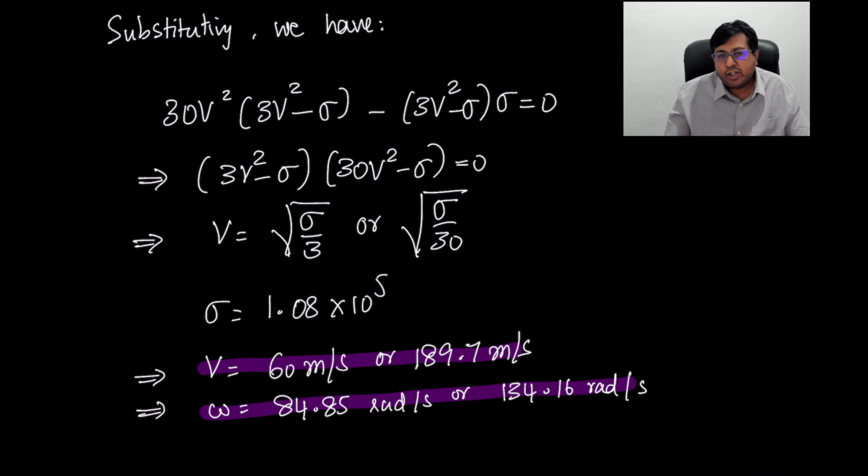Overall, to summarize everything that we have done so far, we started out assuming that we have an airfoil undergoing a heaving and a pitching motion. Heaving motion is up and down, pitching motion is a rotating, twisting motion. We thought of this as a 2 degree of freedom system in order to derive our equation of motion. And then we asked, what if we have a general equation of motion? Using the simple airfoil, we tried to understand what flutter is.